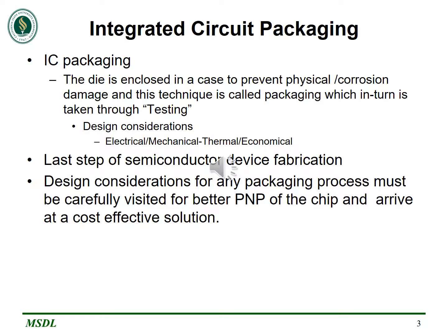In this slide, let's discuss integrated circuit packaging. All integrated circuits are enclosed in a case in order to prevent physical and corrosion damage. This process is called packaging. This is the last step in device fabrication. The package is further taken for post-silicon testing. The steps of packaging must be followed very carefully for better power and performance of the chip and also for a cost-effective solution.